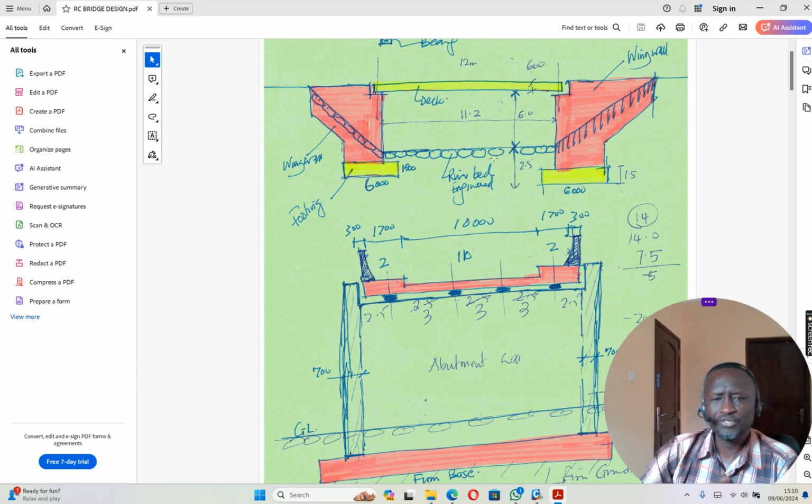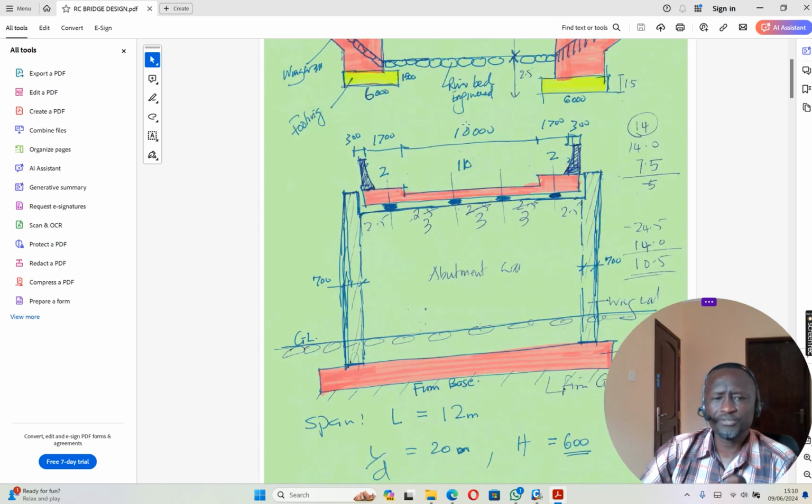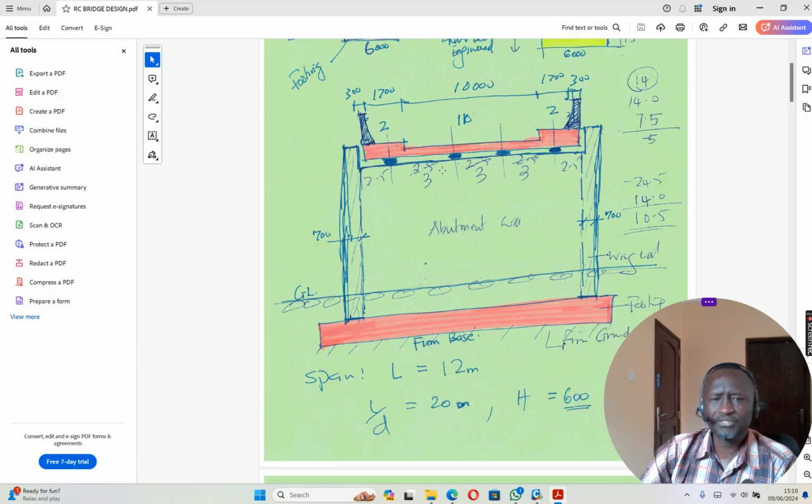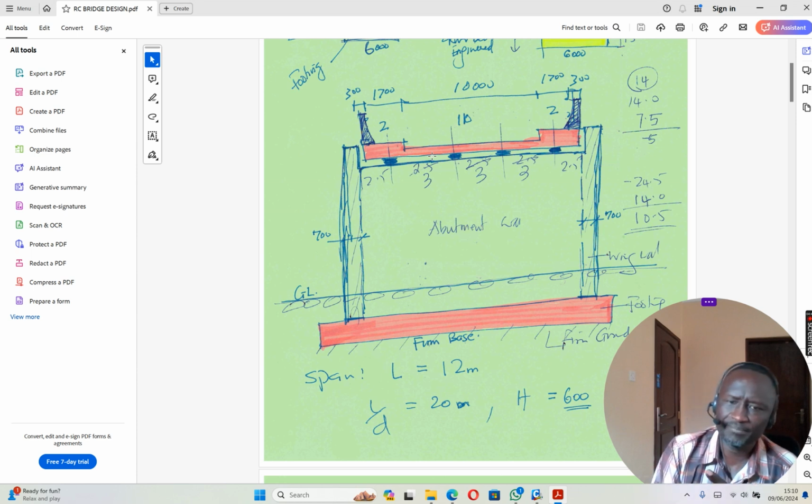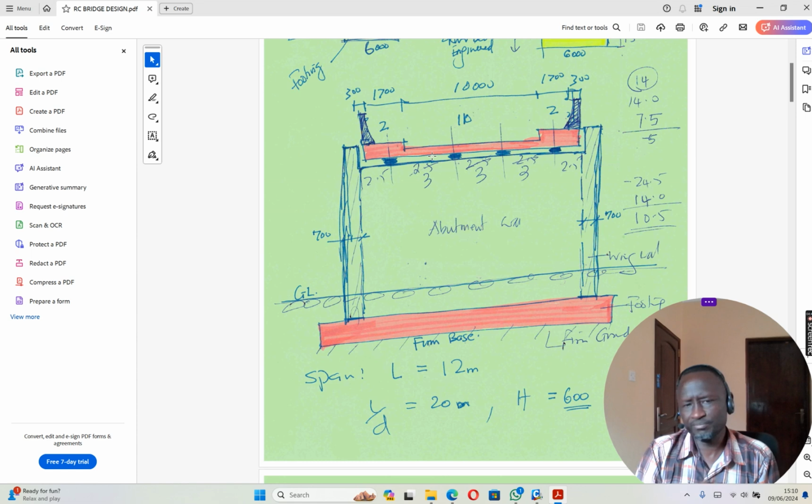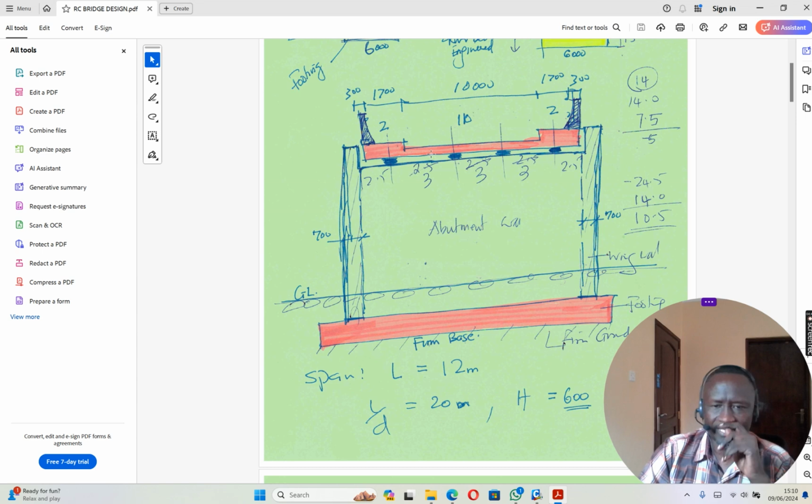You do a sectional view. You need to understand, you look at the typical section. For a slab bridge, normally bearings can be even at 1 meter to simulate exactly the 1 meter philosophy of slab design or wall design, the linear stuff. But for demonstration purposes, we adopted 4 spaces at 3 meters.